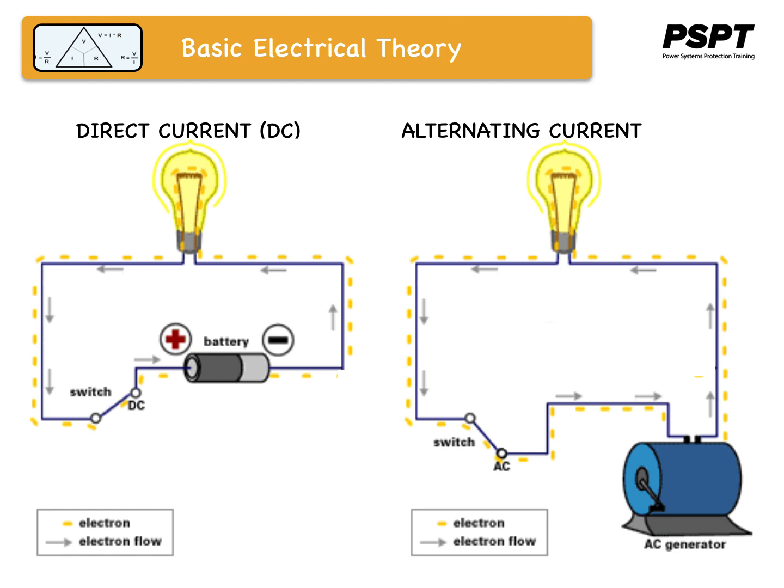The diagram on the right is alternating current, and it's diagrammed such that it has a generator. In this case, it's a hand-driven generator, and it is constructed in such a way that the current is alternating. Half the time it's flowing in one direction, half the time it's flowing in the other direction. And if that change is fast enough, like we have in North America, 60 times a second, you don't even notice it in the flicker of a light bulb because it is too quick for your eyes or even the light bulb to null out and produce zero output.